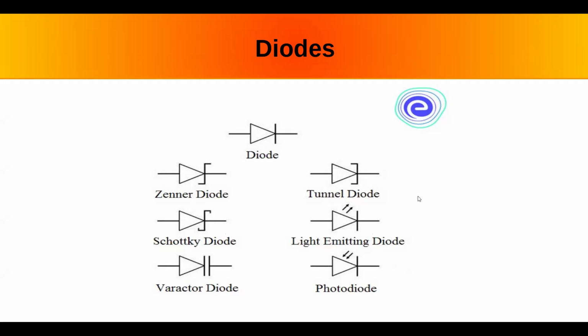It turns out all diodes, all p-n junctions emit light. As an electron crosses the barrier, it has to be up to a certain energy level to get there. When it gets across the barrier and recombines, it releases that energy. And that energy is dispersed as heat and light and electromagnetic.